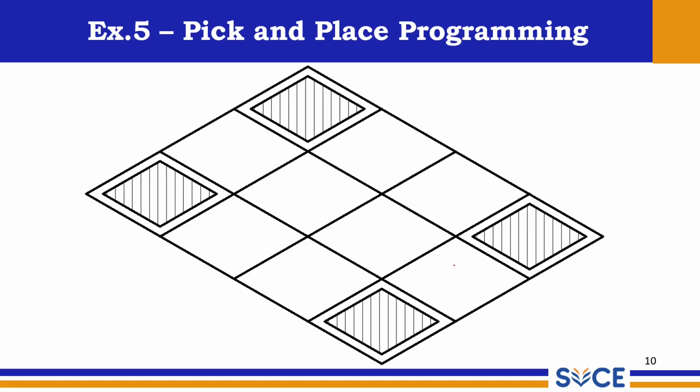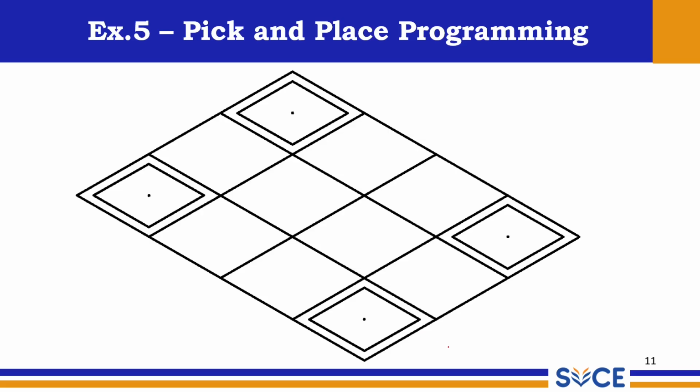See, you have got a pallet. You plan in such a way that in all cases there should not be 4 rows and 3 columns. There is no hard and fast rule. You only plan, it is based on your requirement. This hatched portion is the box size, so this is the unit part. And these all are the 4 corners. Why? Because these 4 points we are going to specify in the program. Now, these are the 4 extreme points, but not these corners; they are the center points of the 4 extreme unit loads.